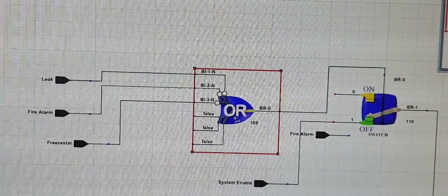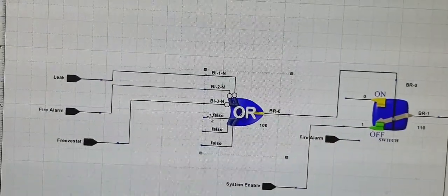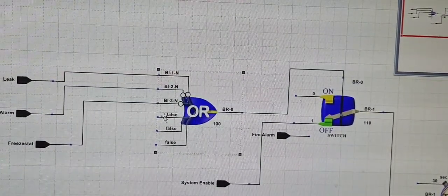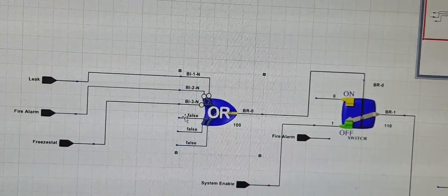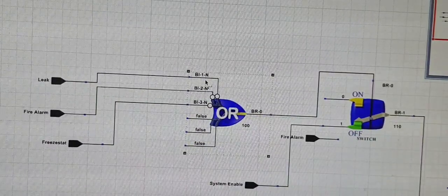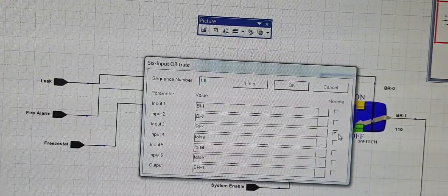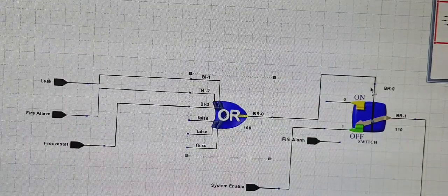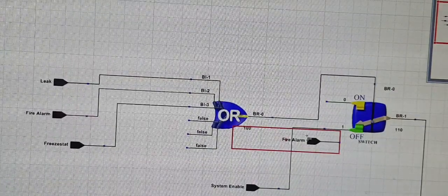So I'll show you. If any of these conditions occur during the time of the system operation, then you don't want the system to run. So you want the system to shut down or not turn on the system, and someone from the maintenance of the facilities will come and have a look at the system, make sure everything is good, and reset the alarms. So if there's a leak, then okay, let's just remove the negate. Right now we are assuming the conditions are all 0, so it's not going to enable this. So everything is normal. I'll just remove them.